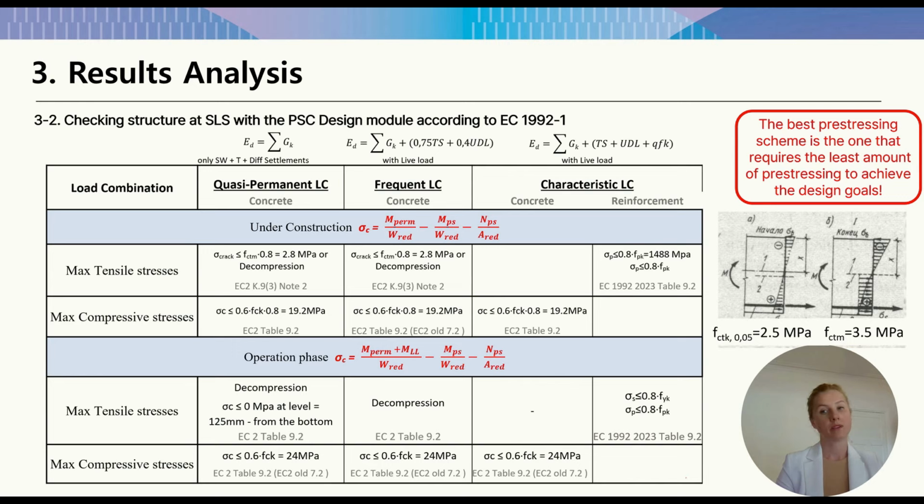Thus, creep strains increase, and so do displacements in the joints and the bearings. In addition, a large number of cables leads to overloading of the cross section during casting and generally worsens the quality of the structure.